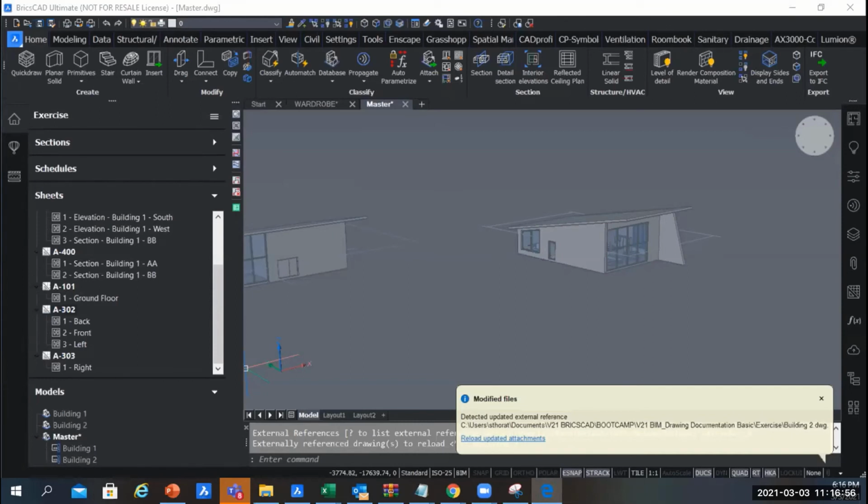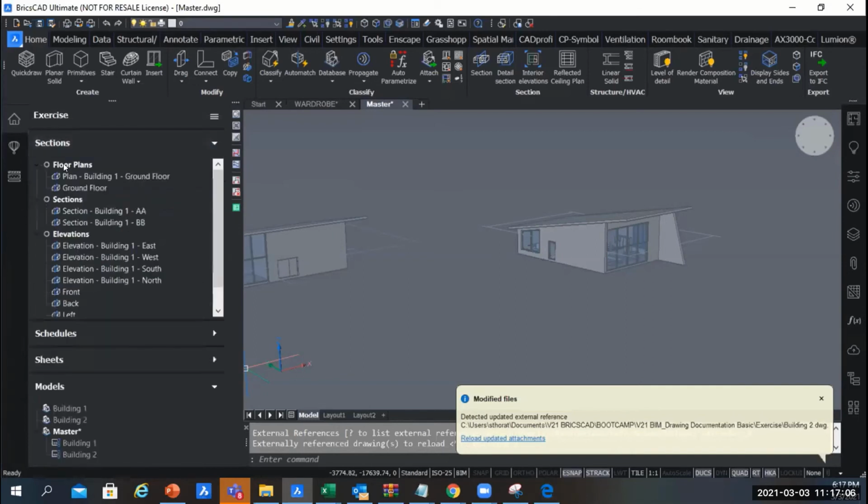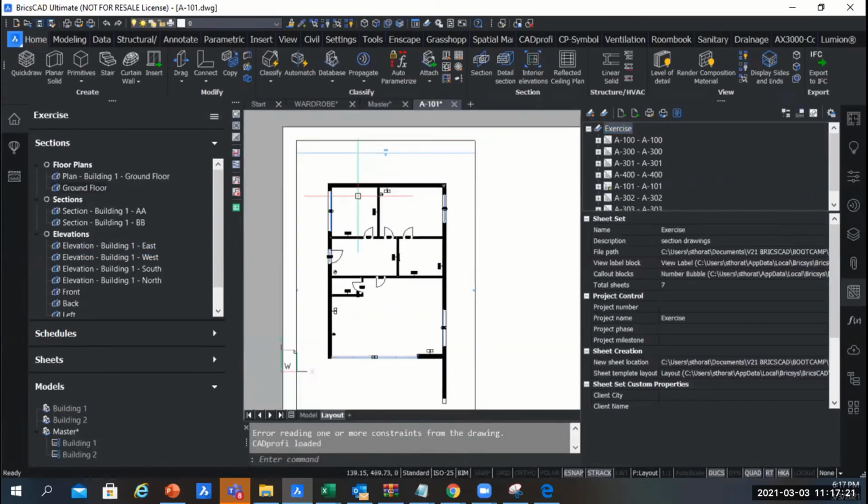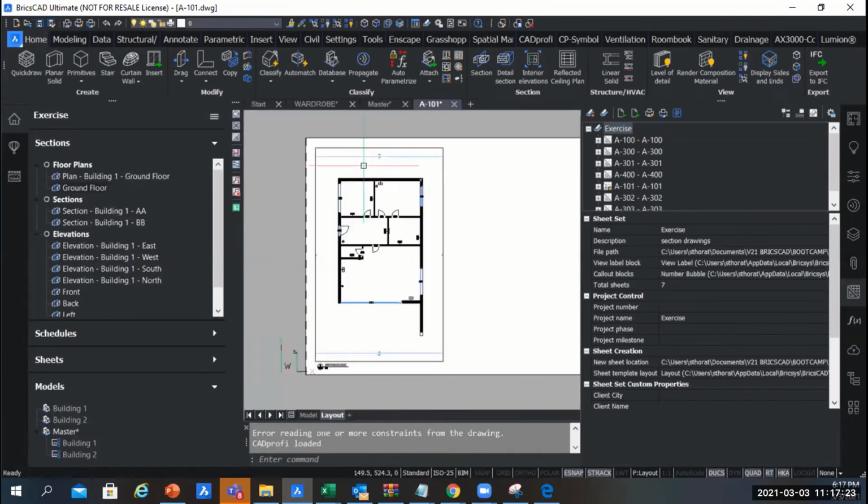Then we check on the generated drawings to see the resulting drawing of the section ground floor. We will right click on the ground floor. You can just go to the section view also. Just go to the ground floor, right click on the ground floor, and we're just gonna say display the section result. There you go. Your building number 2 has the section result right here.